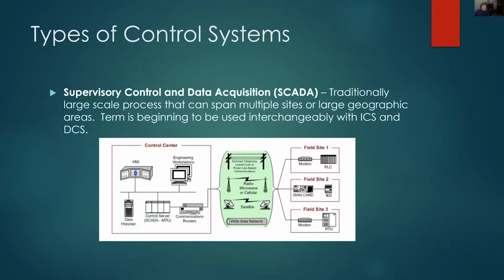And this is one of the reasons why industrial networking and industrial security is becoming such a big deal, and one of the reasons it's so difficult to deal with is you're dealing with a lot of legacy equipment and a lot of legacy protocols, and building stuff on top of them and adding complexity and merging all this stuff together, and then trying to push all of that up to the enterprise network through a firewall and a DMZ, and do it in a way that protects your data, but more importantly, keeps your process up and running without shutting down so you don't lose money, and do it all in a safe manner.